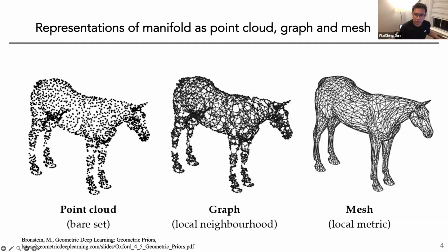Or to put it the other way, if you try to represent this horse in a very perfect manner, I would have some very tiny elements to model the eyelids or maybe the nose. And those things are actually really hard to resolve because it needs a very high condition number to solve in a conventional finite element. So the idea we want to try is, is it possible to separate the need for the geometry to have a very fine mesh, while we can still capture the necessary geometry effect, while addressing the need for giving enough freedom for our solution field.